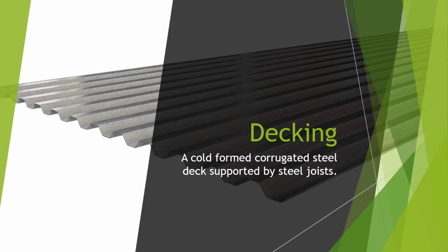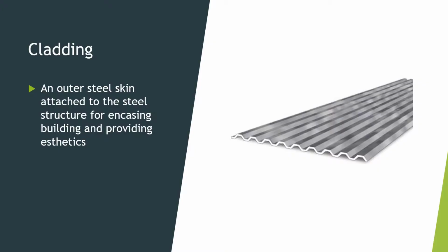Always keep good housekeeping when you're on that deck, because you can kick something off quicker than you realize. And we always follow the regulations and act for our fall protection. Always 100% tie off, and that's mostly required on decking. So keep all that in mind, and we shall be safe laying our decking.